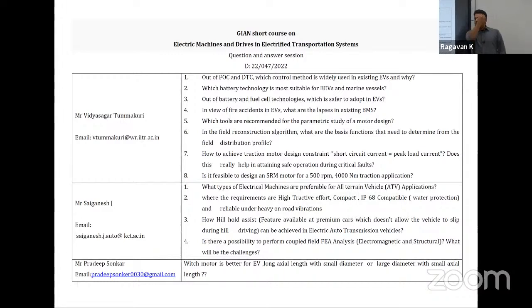Like you even talked about this morning, the idea of the inverter. What's it called? Not a staggered inverter, but a shifted inverter, I think. So that idea basically was you would have less current, so even if one gets damaged, the other one continues to operate. Or if you have a double layer winding, for example. So there are ways in which you can manage, and dual layer winding is something you can take a look at and see if that's potentially an option for you, where even if you have some fault.